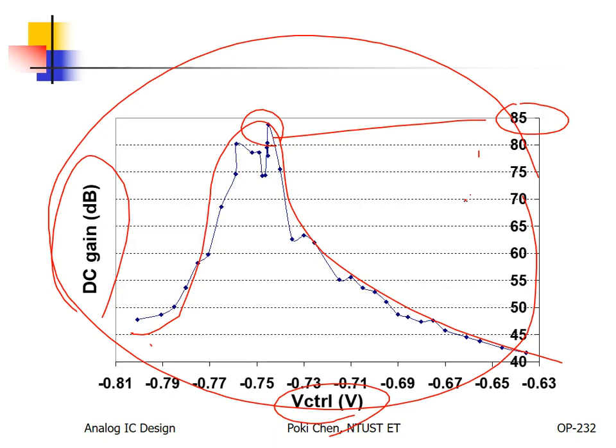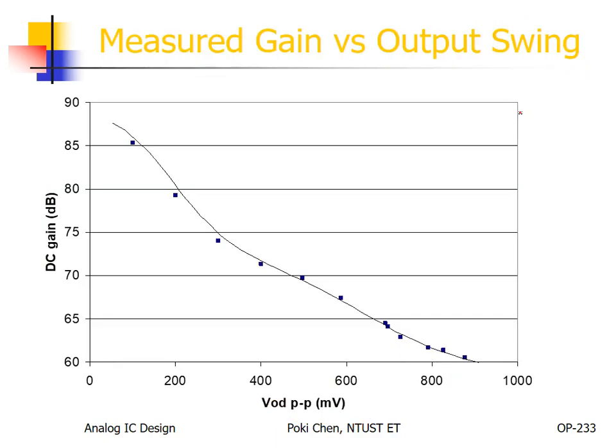Well, it's really amazing. 80 dB in linear scale means 10,000, right? Wow, a single op-amp can offer you more than 10,000 in gain. That is really fantastic. Again, without positive feedback, you cannot make it. But you need to be very careful about the stability problem. A stand-alone op-amp is more likely to oscillate, so you need to put it into some kind of negative feedback control for your application.